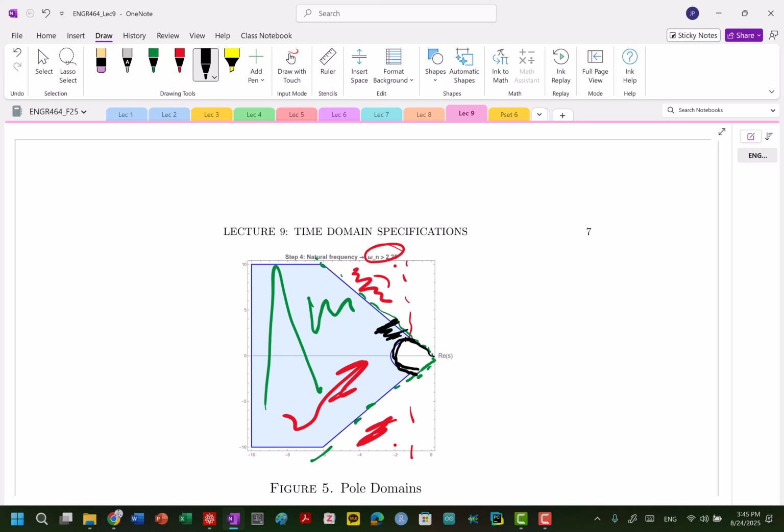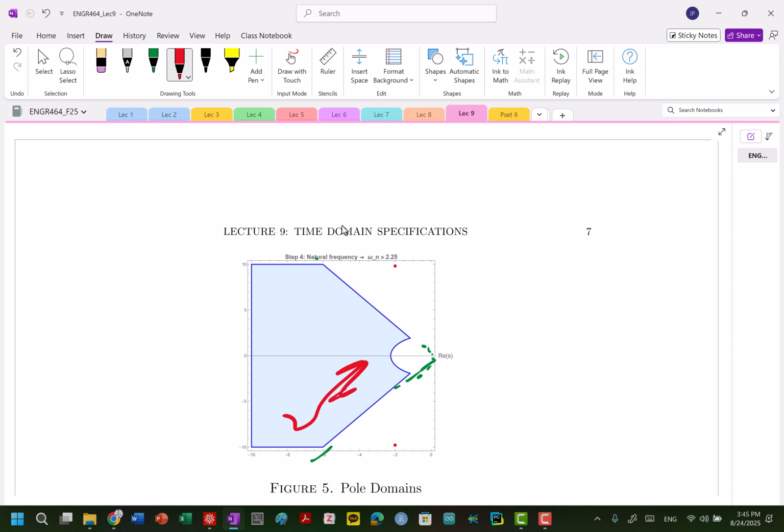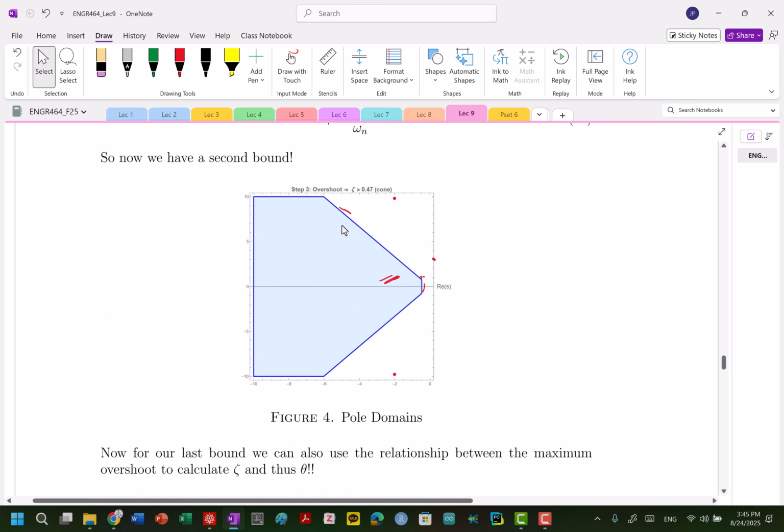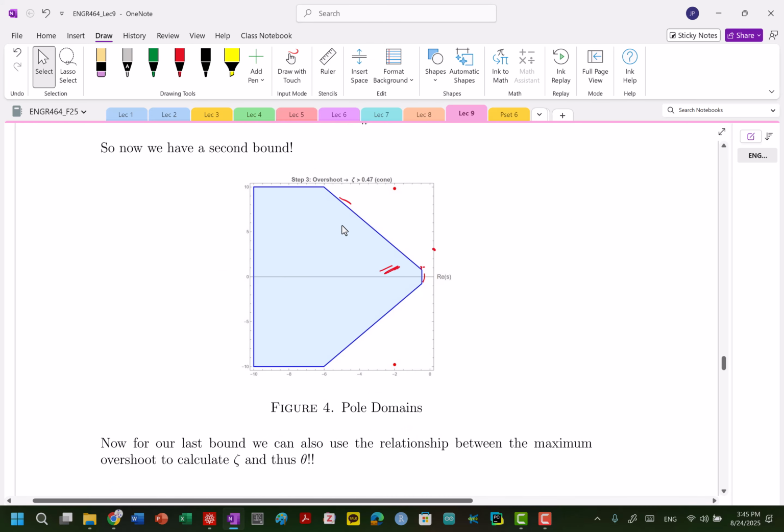Actually, you can just kind of wish there was a circle. It basically extends something like this. So anything that's beyond here works. That shaded-in region, which I'm inelegantly trying to show, is our design region. And we see that we failed once we had that condition related to the angle, which is zeta, which was our maximum overshoot.